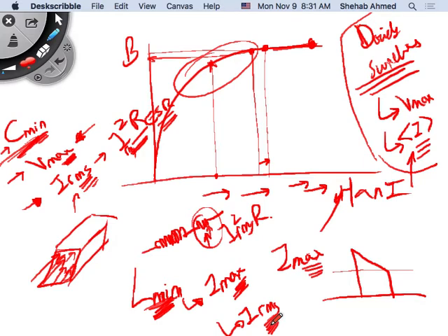But not all wires can fit in any core, right? Because if you look at our transformer, for example, we cannot put a wire that's this big in diameter around a core with a certain core window. You cannot, right? So there is a certain range of wires or types of wires that you can use on a certain size of inductor core.